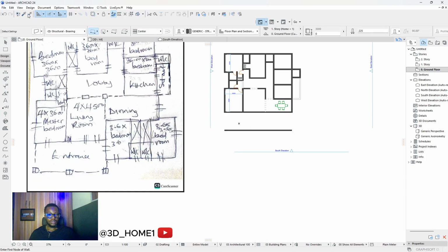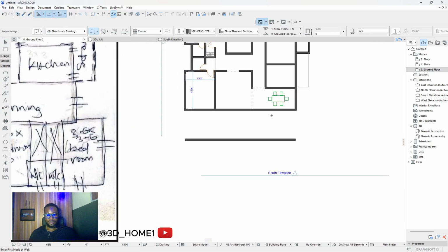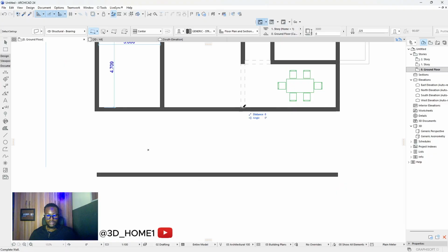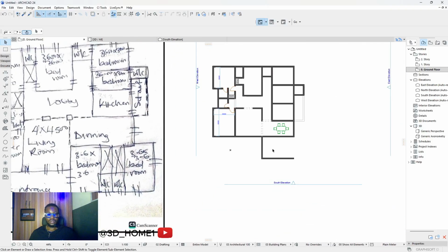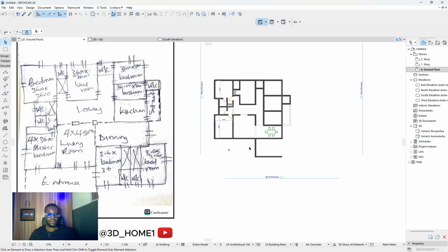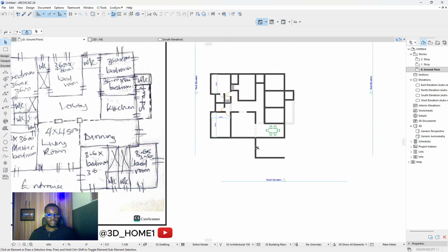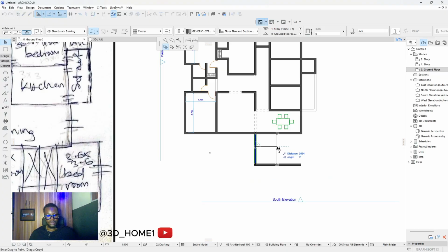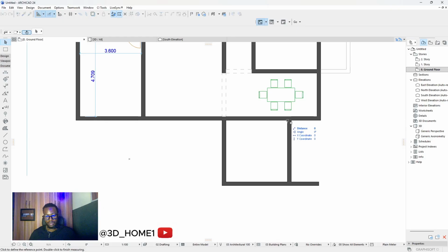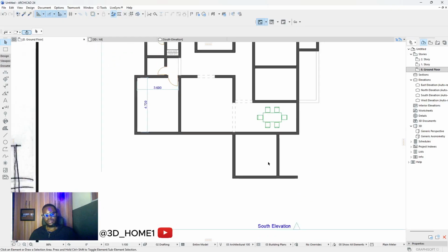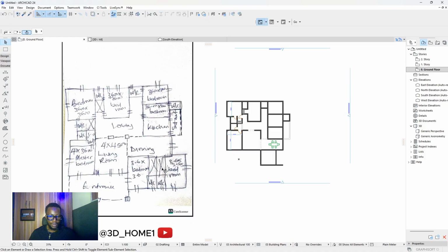and this is the pick up parameter tool. You can easily use it to pick a particular object, or component. So now we need another 3.6 this way, 3,600 this way, like this. Let's confirm this other measurement. Yeah, 3.6.